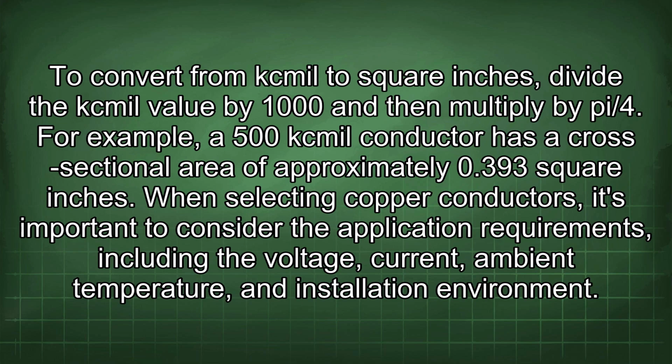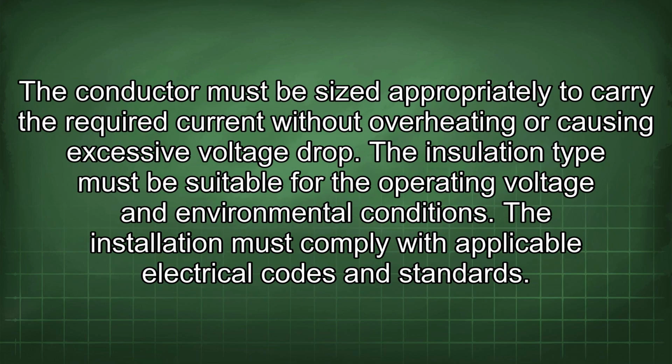and installation environment. The conductor must be sized appropriately to carry the required current without overheating or causing excessive voltage drop. The insulation type must be suitable for the operating voltage and environmental conditions. The installation must comply with applicable electrical codes and standards.